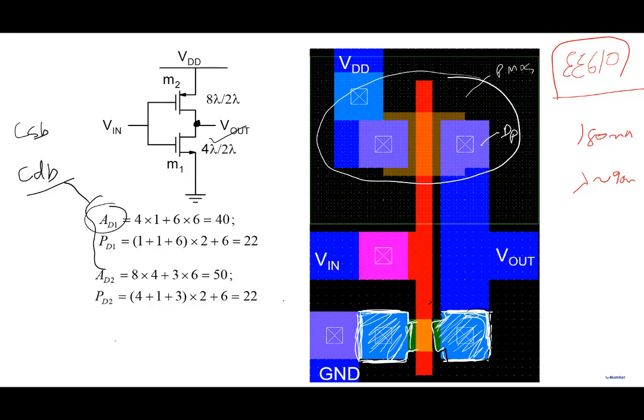One of the very common mistakes people make is they take a schematic and start simulating it, and the simulator has no information about, let's say, area of the drain and perimeter of the drain. So it will just put the value of the capacitor as 0, or take some default value which is wrong. You'll get all wrong results for your delay, for your unity gain frequency, everything, because you don't have the proper area and perimeter of the drain if you don't feed it into the simulator.